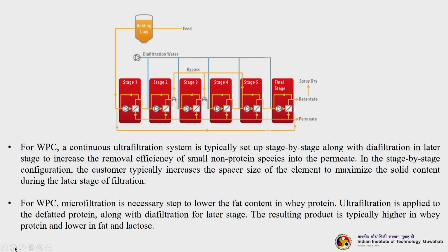A continuous ultrafiltration system is typically set up stage by stage. It is not a single ultrafiltration membrane that will do the job. They are stage by stage or in series, along with diafiltration in later stages to increase the removal efficiency. In between a few ultrafiltration stages doing the WPC, some diafiltration membranes are also installed. In the stage by stage configuration, the customer typically increases the spacer size of the element to maximize the solid content during the later stage of filtration.